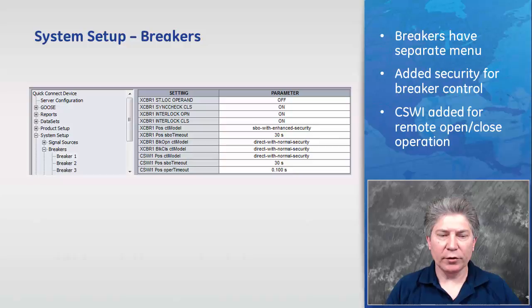Next, we'll look at breakers. The difference in this version is that we separated each one of the breakers into their own menu and added some security for control. So an additional logical node, CSWI, has been added for remote open and close operation of each breaker.